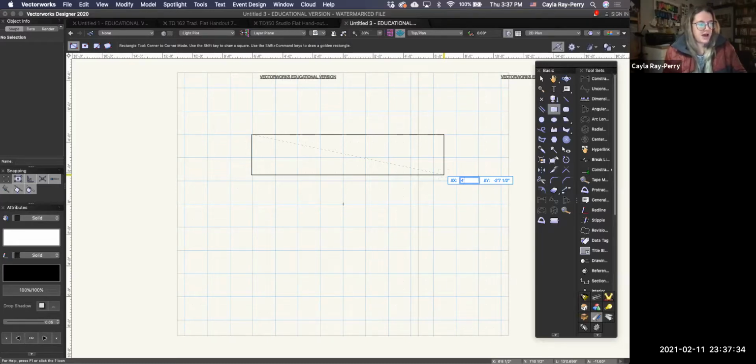And then if I tab again, remember it's in 1/2 inch scale, but you're going to talk to the computer in real life terms. So 4 feet, which is actually 2 inches on my scale drawing, but we're going to talk to it in real life terms. So 4 feet. If I tab again, it automatically makes that 4 feet for me. Okay. And now it's going to ask me the other dimension, the Y dimension, the up and down dimension. What do I want that to be?